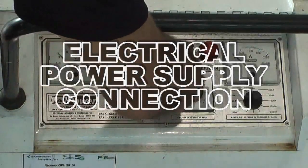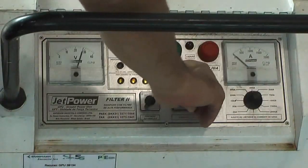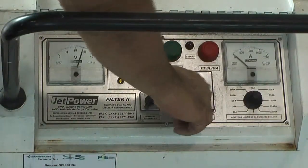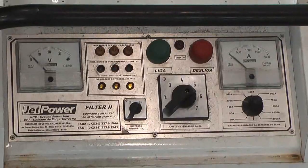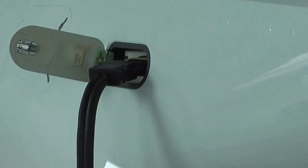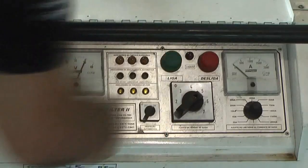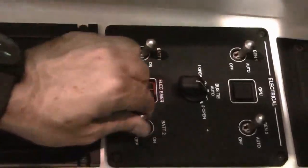Electrical power supply connection. Turn the GPU on. Adjust the GPU output voltage to 28 volts. Turn off the GPU. Open the airplane power supply receptacle door. Connect the GPU cable to the airplane power supply receptacle. Turn on the GPU. Turn on the batteries.